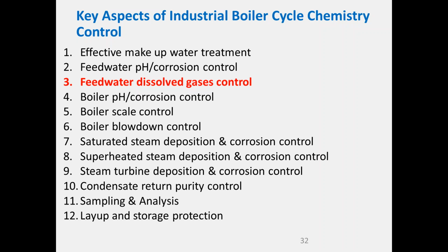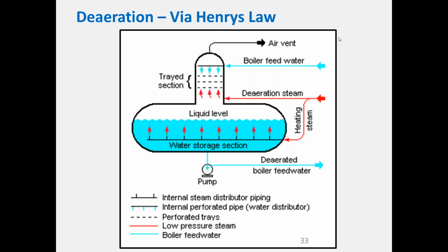For dissolved gases, that's the next one. Normally people use a deaerator, and here we use Henry's law. So we have a vessel, and the boiler feed water is sprayed in. We have some oxygen-free steam that's pushed into the bottom here. That flows up, and by Henry's law we get gas exchange, and that steam strips the oxygen from the boiler feed water, and that'll be ejected out the vent. And then the water falls down. It's picked up some heat as well, and then it will remain in what we call the feed water storage tank, and that may have some steaming in there as well.